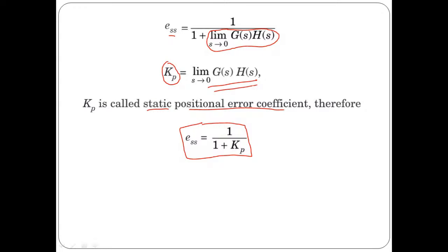These formulas you have to remember, because in GATE, based on these formulas directly you have a numerical for 2 marks. Like, a system is given to you, they also mention what type of input they apply as an excitation, and your objective is to calculate the value of steady state error, maybe for type 0 system, type 1 system, or type 2 system. In the coming portion we are also going to discuss what exactly type is and what exactly order is, but for the time being let us consider that this is the formula to calculate steady state error when the system is excited by unit step input signal.